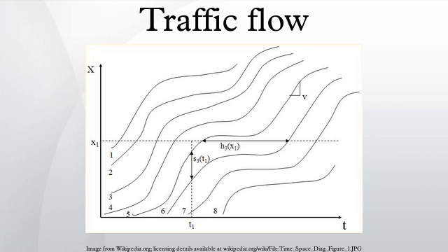The traffic light example depicts N-curves as smooth functions. Theoretically, however, plotting N-curves from collected data should result in a step function. Each step represents the arrival or departure of one vehicle at that point in time. When the N-curve is drawn on a larger scale reflecting a period of time that covers several cycles, then the steps for individual vehicles can be ignored, and the curve will then look like a smooth function.